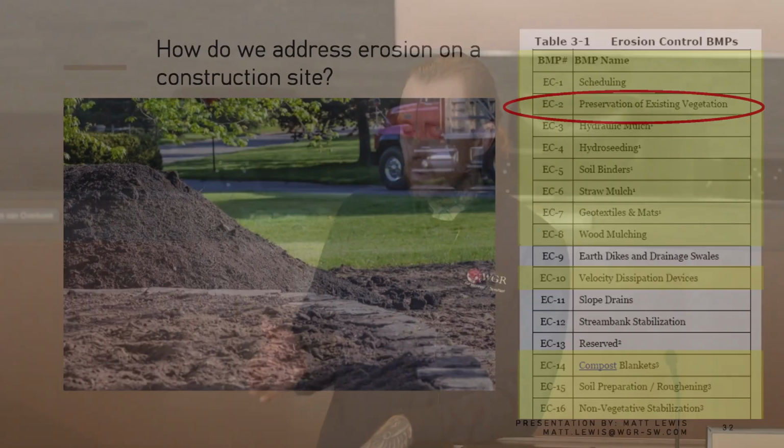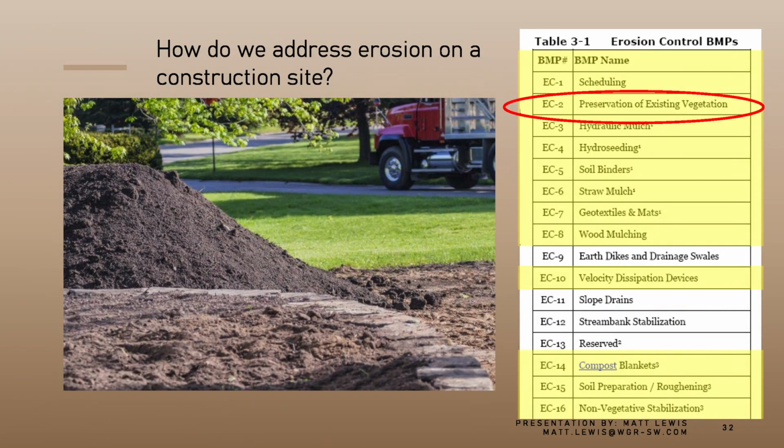So in the new permit, you have this new one, which is preserve existing topsoil. Not a lot of people would think about this, but when it comes to post-construction, you're going to want to see natural vegetation. Usually, if you're dealing with a SWPPP, it will be at least 70% of full vegetated growth.